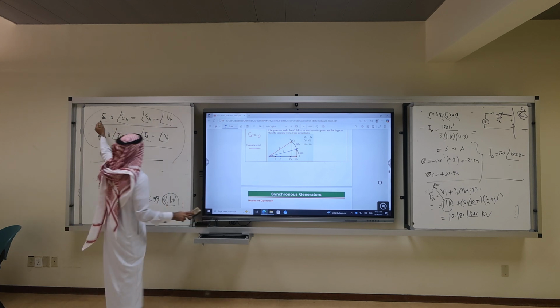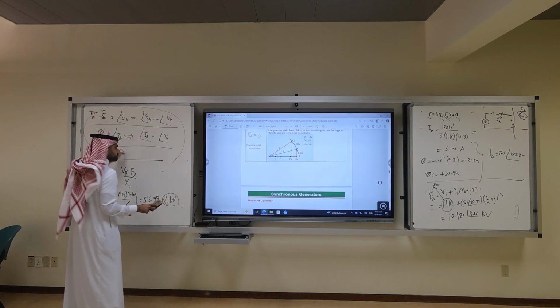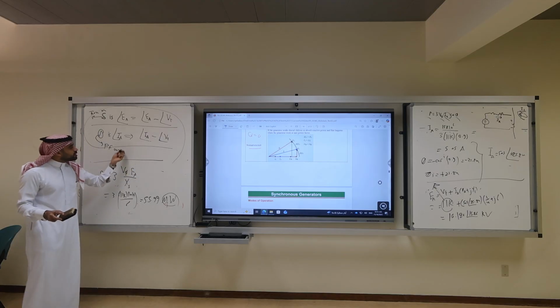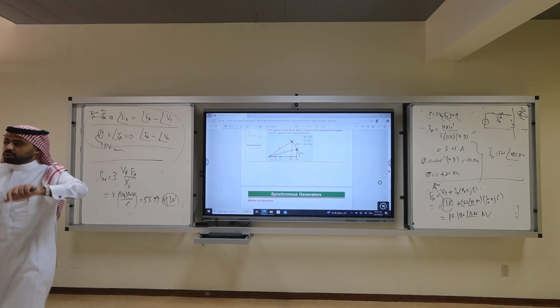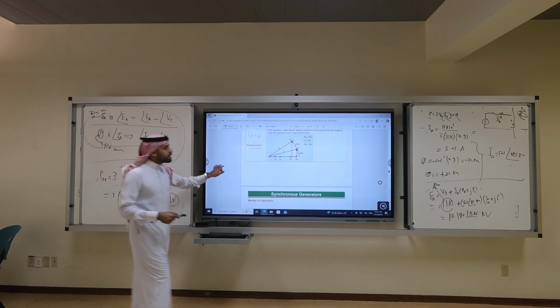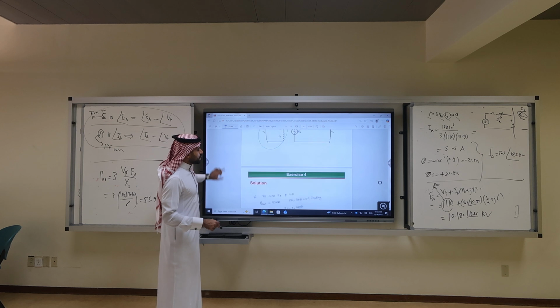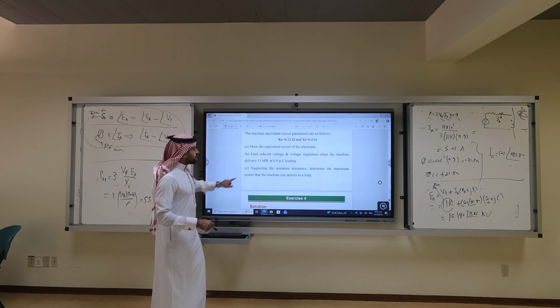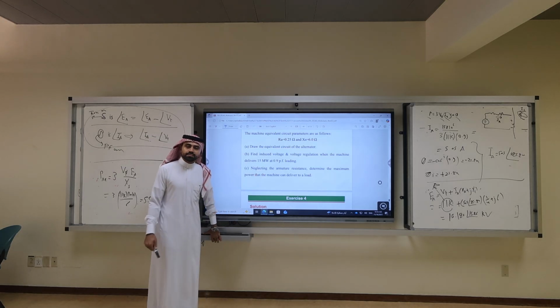This is called the torque angle, and this is called the PF angle. Clear? This one the YouTube teaches you, and this one the torque angle teaches you. Please watch the YouTube now. Today's lecture is very important. This is the maximum. The question asks about the maximum real power. Yes, sine 90. Here the question says, read the question: neglecting armature resistance, determine the maximum power that the machine can deliver.